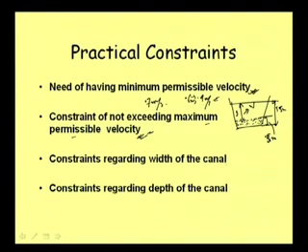Then there may be some other constraints, like constraints regarding the width of the canal. Well, recently I was involved in the design of a drainage canal in one city called Dibrugarh, and with all calculations of how much discharge will be coming from hydrological calculation, I could see that the size required for the canal, if I go for the best hydraulic section, the width becomes, say, 4 meter, 5 meter, like that in some places.